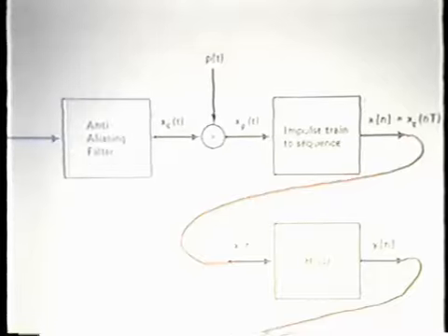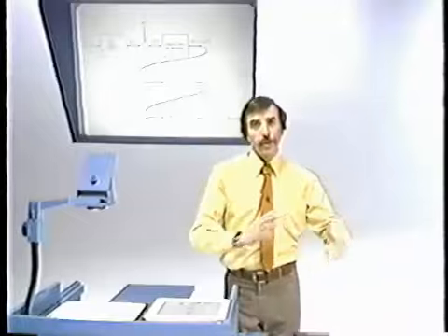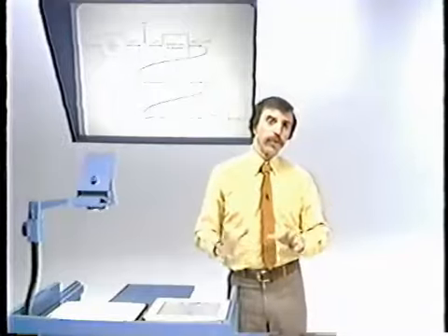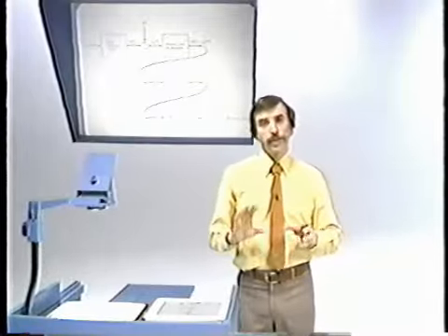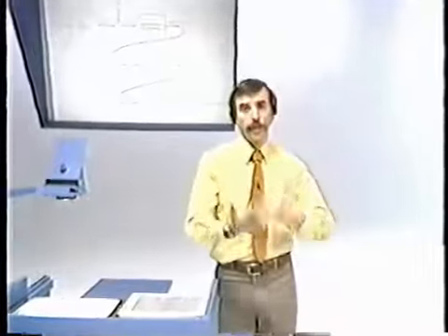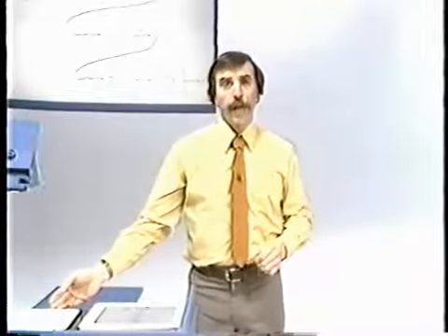And it's important to stress that in this kind of processing, discrete time processing of continuous time signals, except in certain special situations, it's very important to avoid aliasing, because we're going to want to do a reconstruction after we do the sampling and processing. Okay, now this is the sequence of steps in the time domain. Let's examine what happens as a consequence of this in the frequency domain.